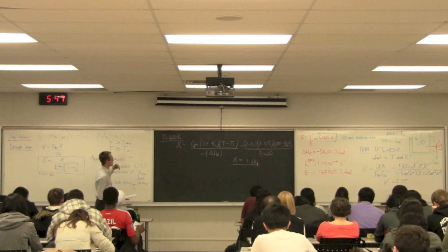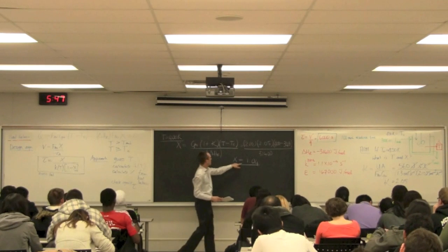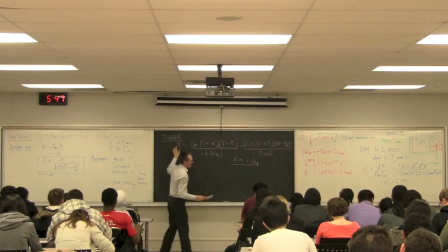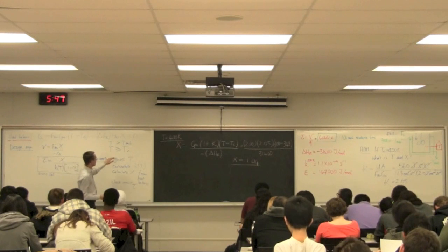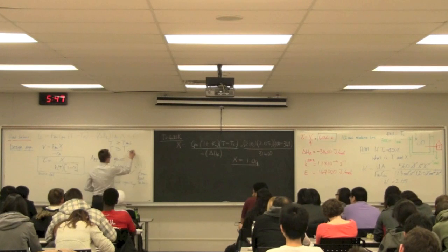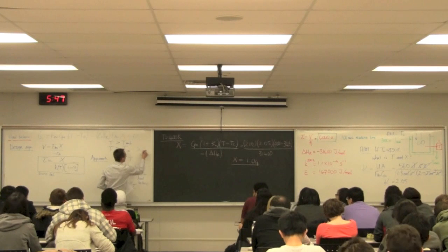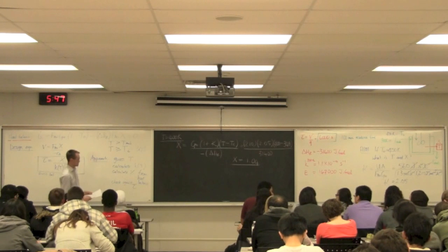In fact, any temperature higher than 400 will give you conversions greater than 1. So there is an upper bound on temperature over here. So we know that somewhere between 349 Kelvin on the lower bound and at most somewhere around 400 is where our outlet temperature was.